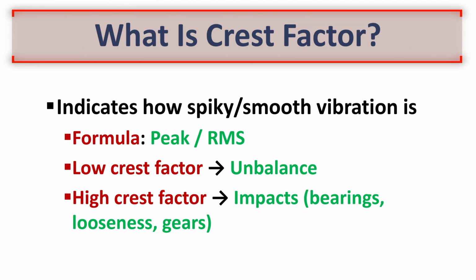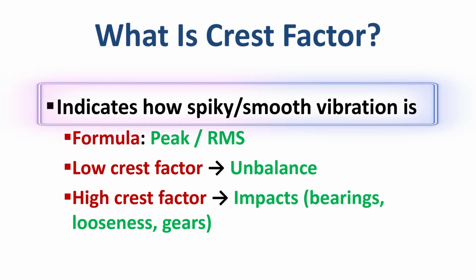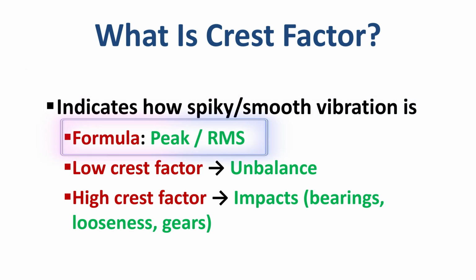Now what is this crest factor? Crest factor is, you can say, the most underrated but powerful indicator. Normally this crest factor tells us how sharp or spiky the vibration signal is. The crest factor is the ratio of the peak vibration divided by the RMS